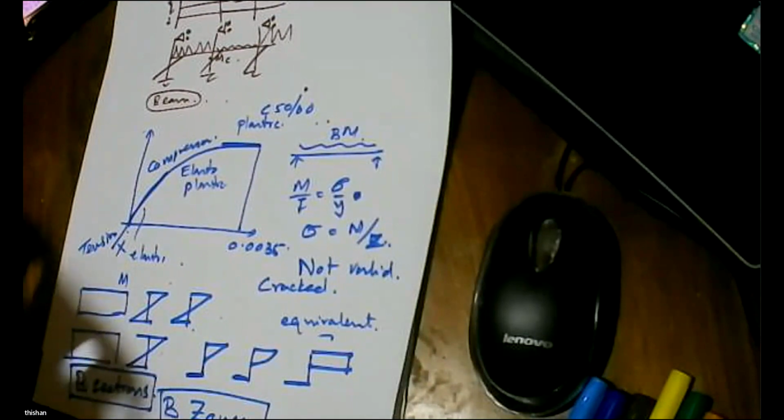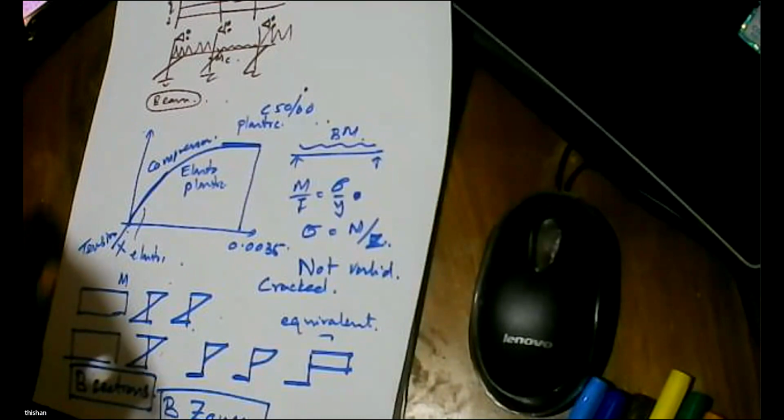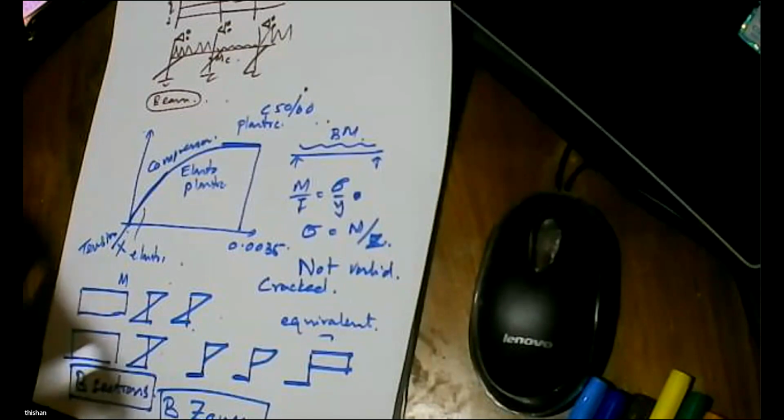So we solved the problem that way, and we reduced the number of piles by 50%, because now our piles will be carrying, for a 1200 pile, up to 12,000 kilonewtons, and a 1500 pile can go up to 17,000 kilonewtons.